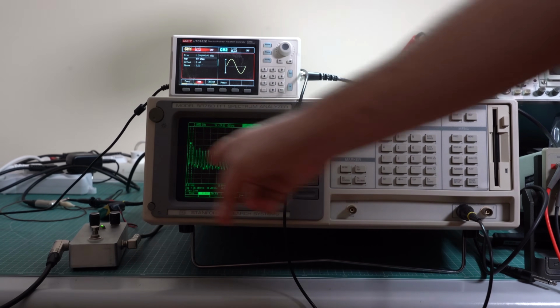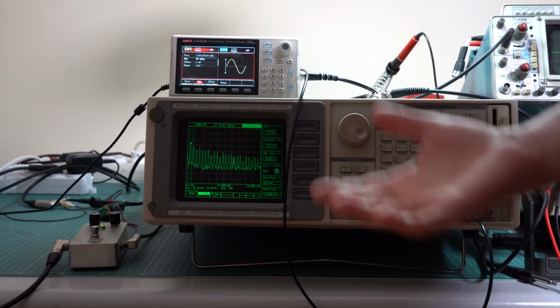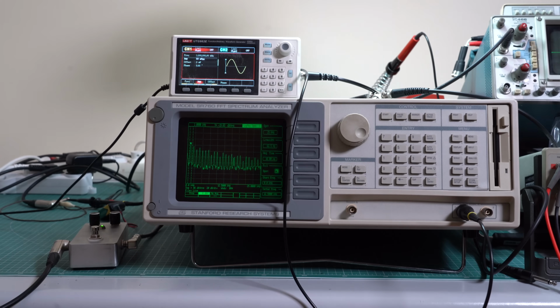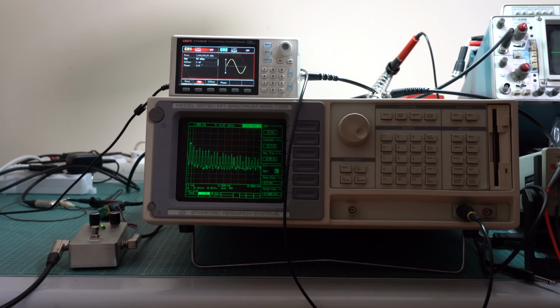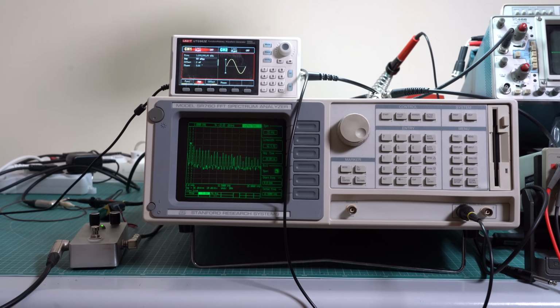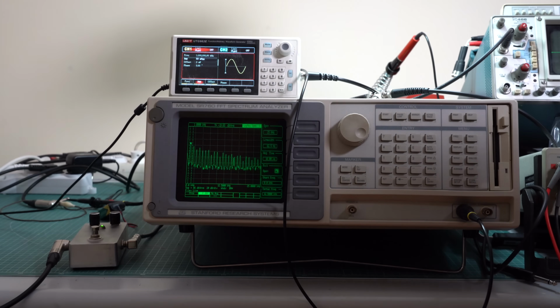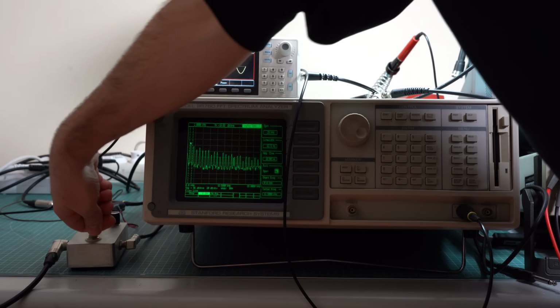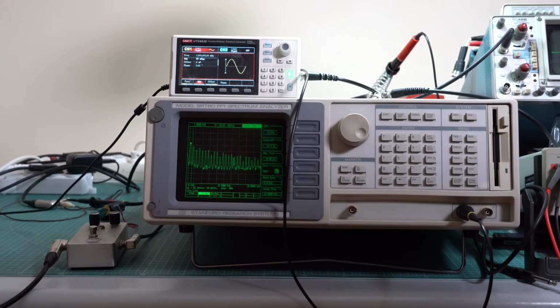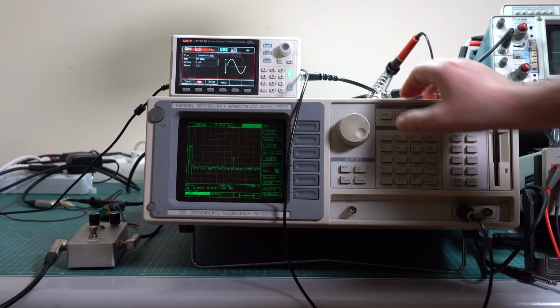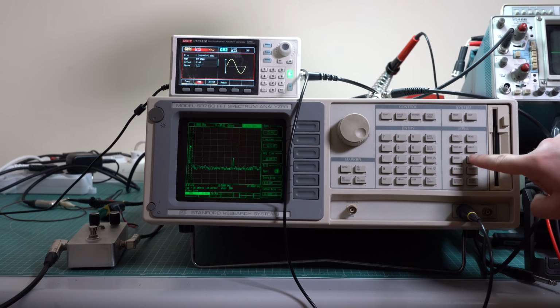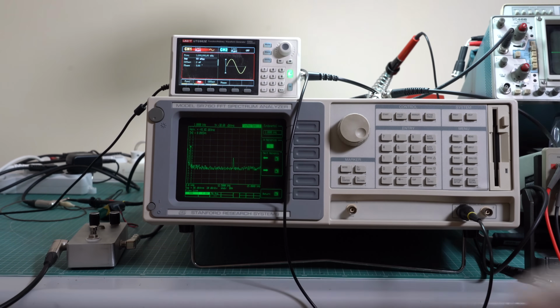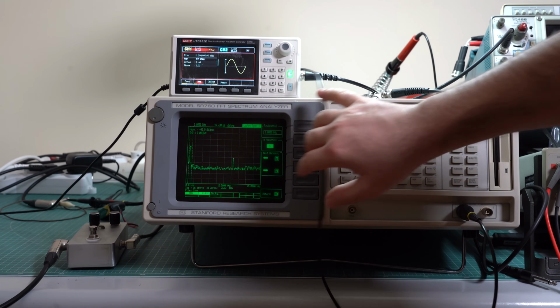And this is characteristic of a system that has tons of distortion, which is exactly what the pedal is supposed to do. Now what we can do in order to characterize how much distortion we have is to measure the THD. So let's reconfigure the spectrum analyzer for this. In order to do this, we have to start it once again, go to Analyze, Harmonic, and then we have to set up a few parameters here.